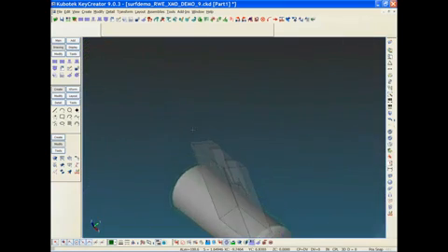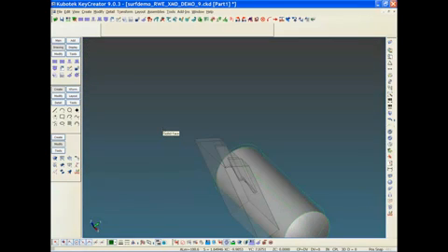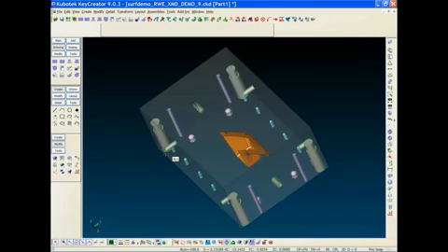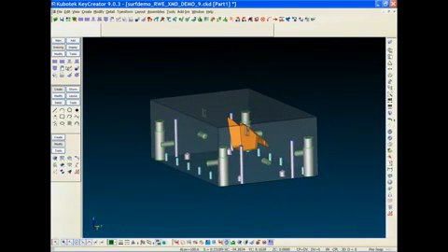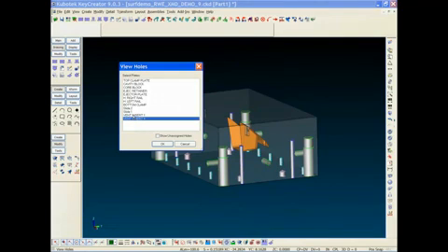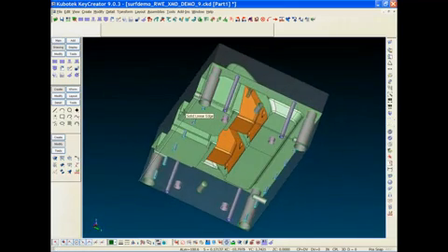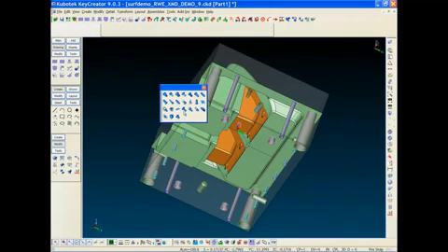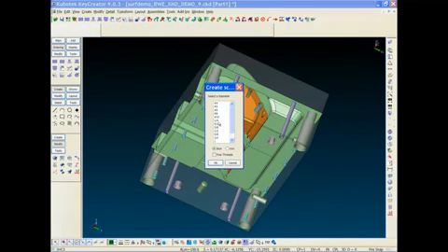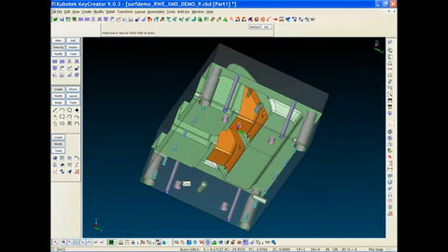And I can go back and trim that stuff later if I choose to. If I don't want to, I don't have to. But you can do everything with one big solid block and just your surfaces as references. So that really speeds up the mold design process, because the data can get a little heavy with all those rads and fillets and surfaces trimmed to these solid core blocks.